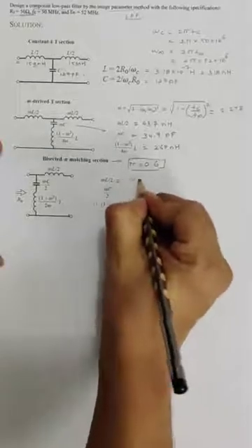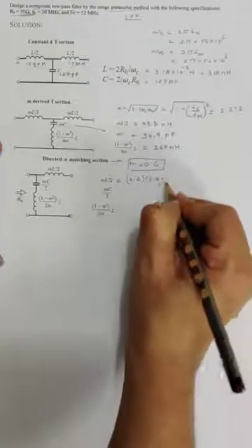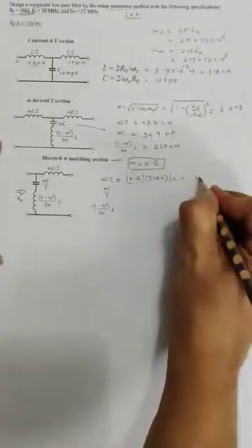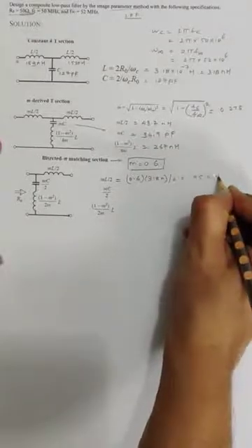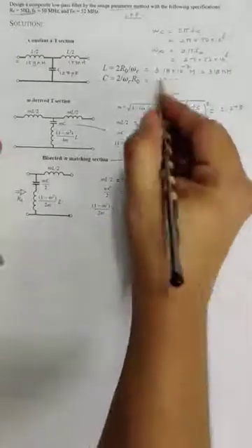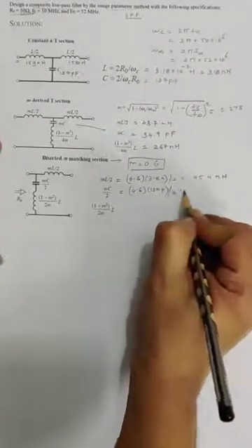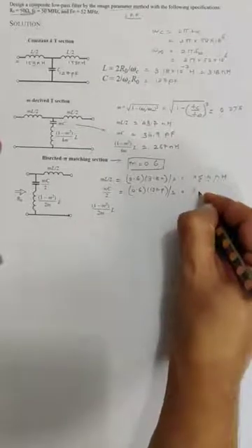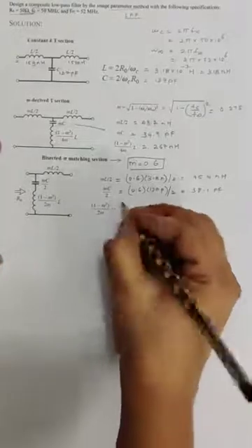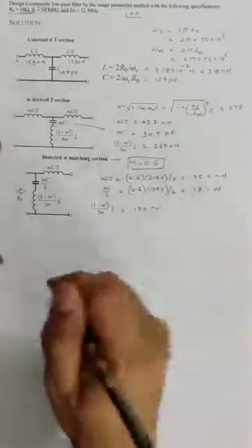So we'll take m is equal to 0.6, L is equal to 318 nanohenry divided by 2, so it turns out to be 95.4 nanohenry. m as 0.6, capacitor 127 pico divided by 2, so it turns out to be 38.1 picofarad. Similarly, we can calculate this one, it turns out to be 170 nanohenry.